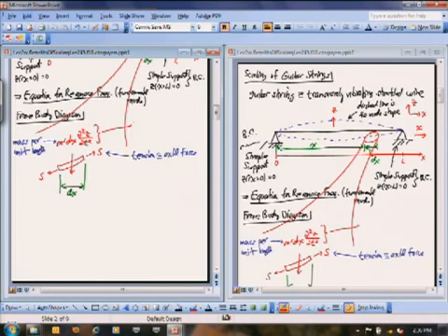Which is mass times acceleration. Okay? And so I've got that force going in the downward direction. What I need to do to create a balance of force equations is find the forces due to these tensions that are also going in the vertical direction. Okay? And so to do that, I need to know these angles here, right? Because I've got a vector of force that's going along whatever direction this element is, but now I need to convert the direction of that force to the vertical direction.